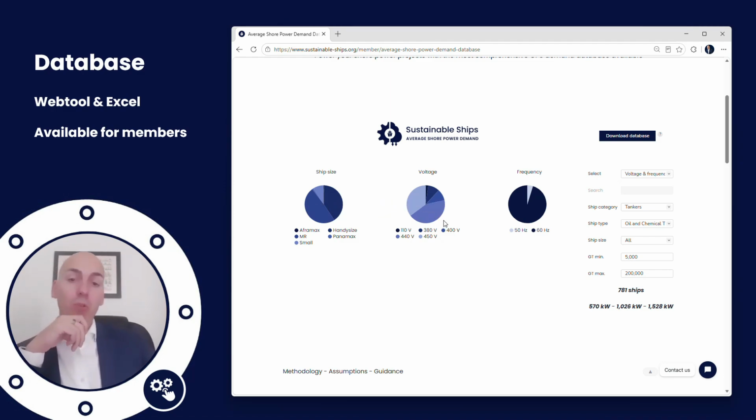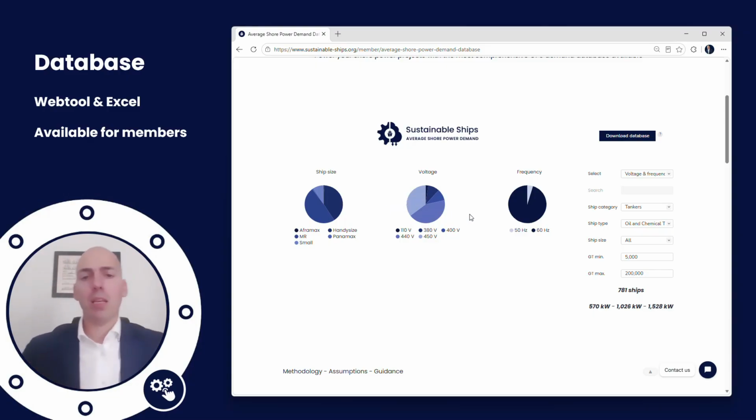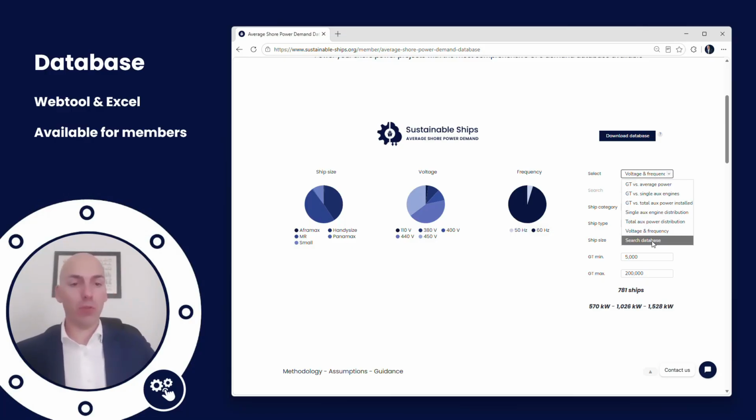Well, that also figures because according to the standard they have to be 440. 450, 440, that doesn't really matter. 400 still, okay, 380, okay, well, you know. Probably we need an installation that is 440 volt. Apart from what the standard is saying, most of the ships can accommodate that. And 60 Hertz, so if we are working in the EU, we need some sort of converter.